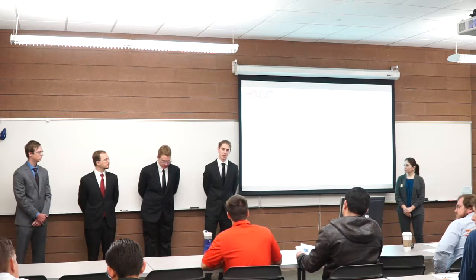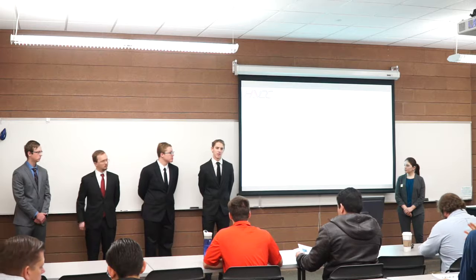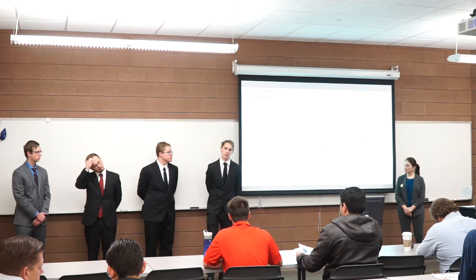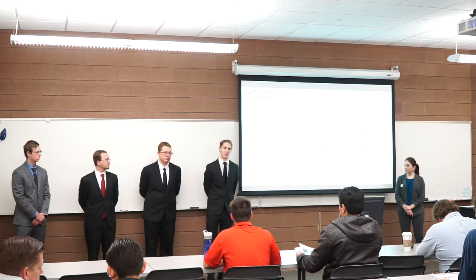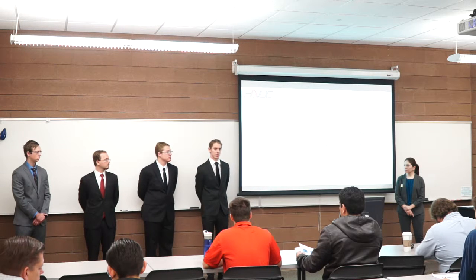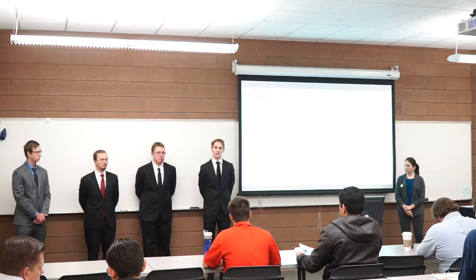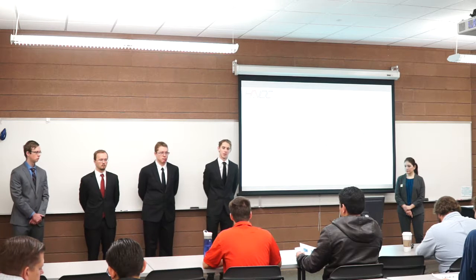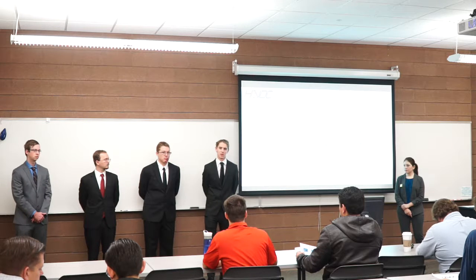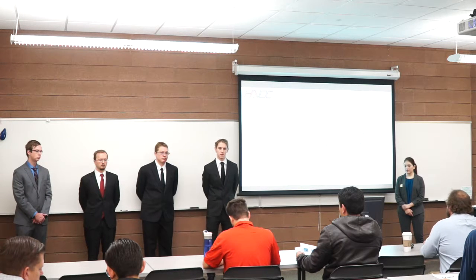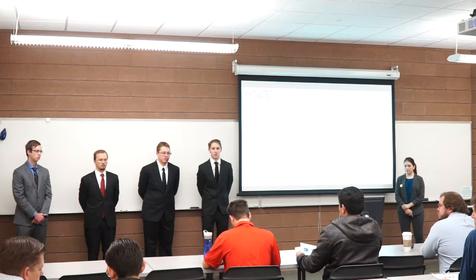One of the things that I don't think was quite mentioned in that section is our specification says that we have to be able to hold 10 pounds. And for a lot of these tests, we use a factor of safety of 2 basically, and double that so that we can make sure that would break our system. Okay. That would have been really good to present on there. Yeah, we should have mentioned that.